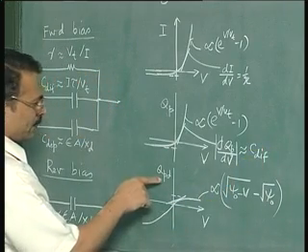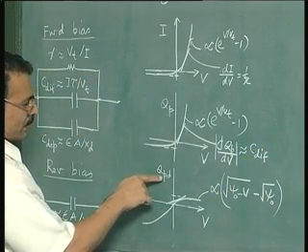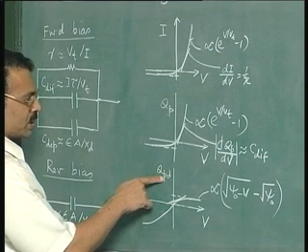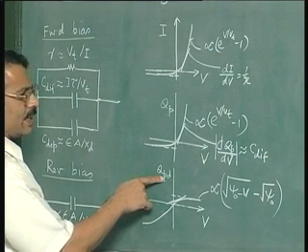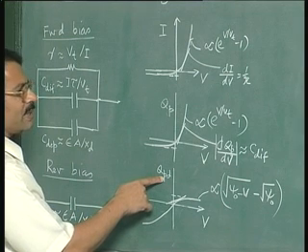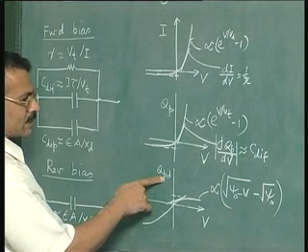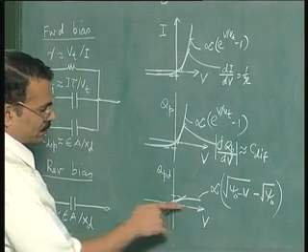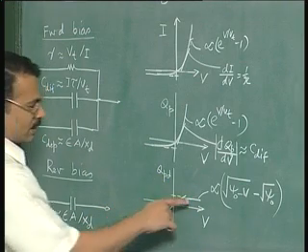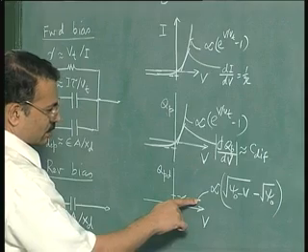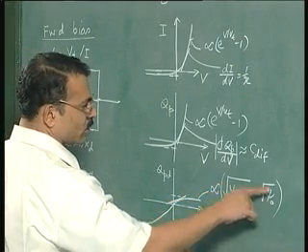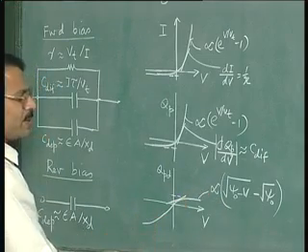Similarly, you take the whole charge that is injected into the device because of shrinking of the depletion layer in the forward bias, and that follows this particular behavior as shown in this graph. Here this particular quantity is proportional to square root of psi naught minus V minus square root of psi naught. This is because of the change in the depletion layer width.